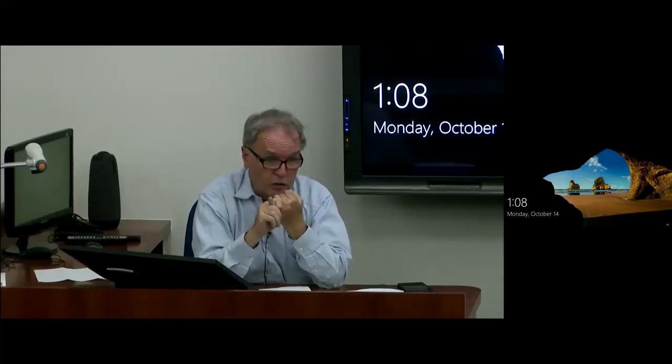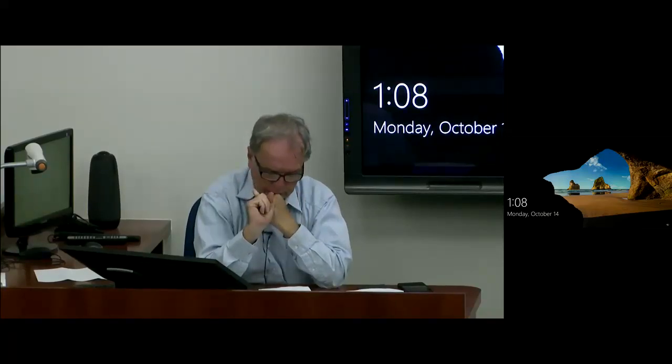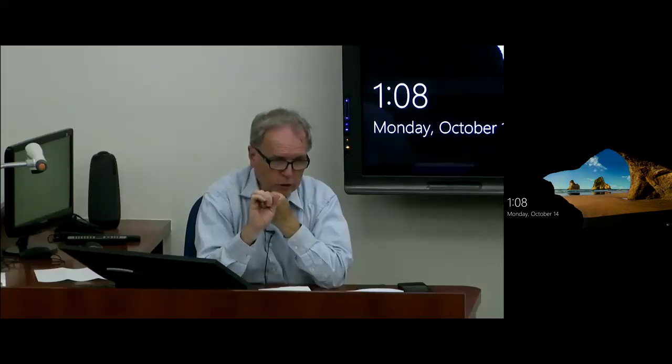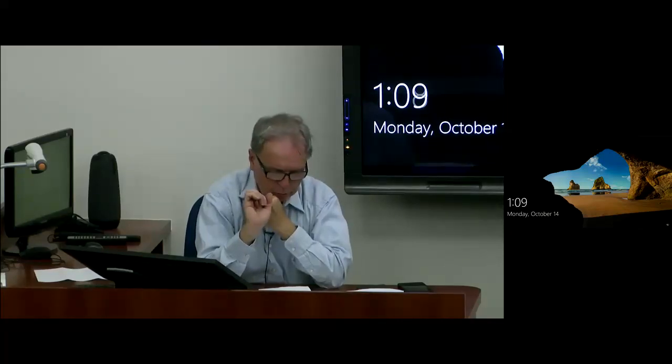Okay, so this is what is currently done: we put layers. And I said a bunch of layers, usually not the same thing. We may alternate a little bit, but we put different layers for different reasons. One of the reasons is to stop diffusion, okay? Another reason is to make a hard layer, right? Another reason might be to reduce friction when we're cutting the metal.